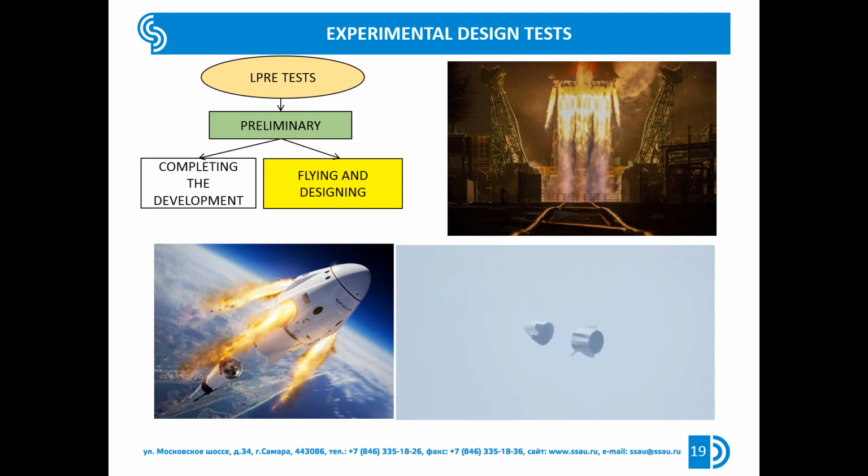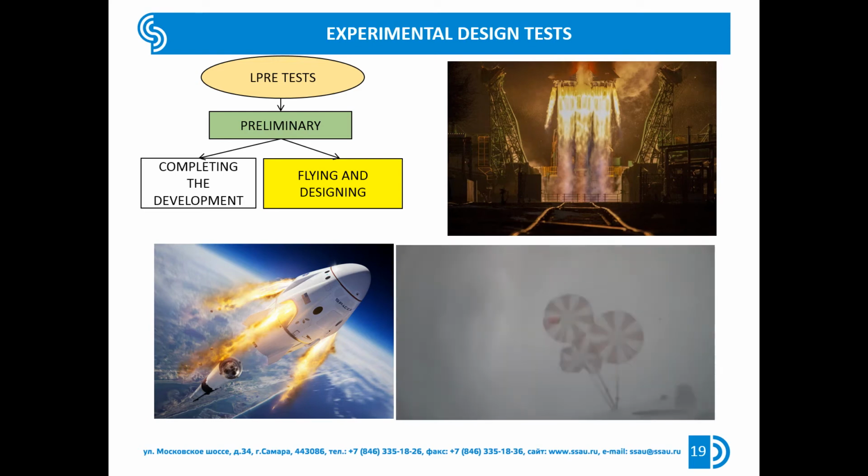The information obtained during flight tests shall first be subjected to operational and then full analysis. A small number of parameters that most closely characterize the performance of the rocket engine is selected for operational analysis. It is checked whether it was functioning normally and what noticeable abnormalities occurred during its operation.